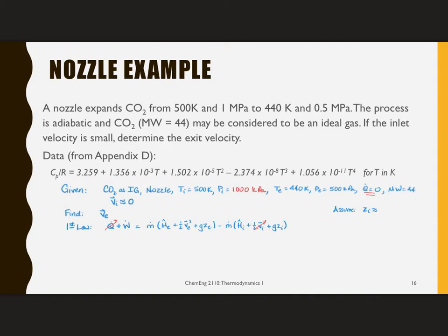So the purpose of these devices is to basically change the velocity so that the material will go further, right? It either adds or subtracts kinetic energy from the system. So if you think about how those are built, typically the change is very small. And I wrote that as ZI equals 0. I meant to say ZI is equal to ZE, or delta Z is equal to 0. Any change you'd have would be very small.